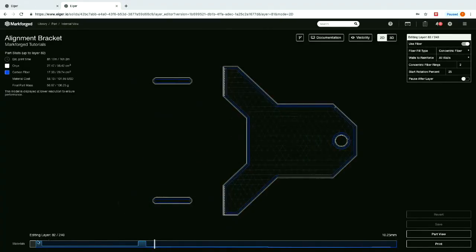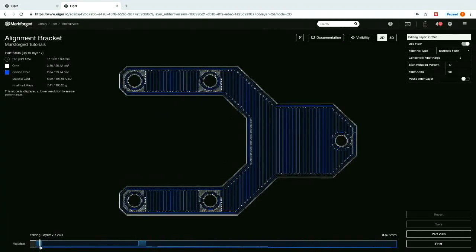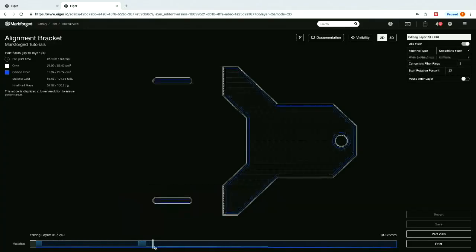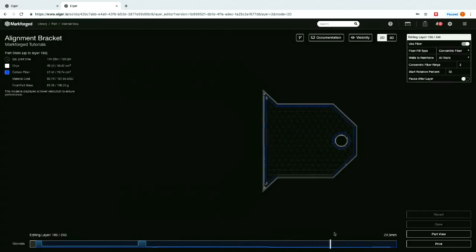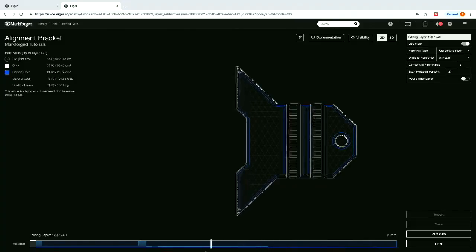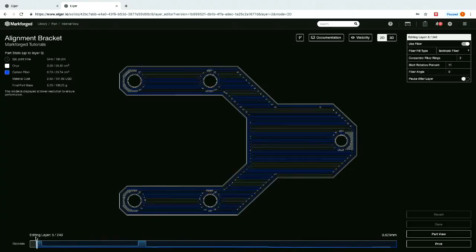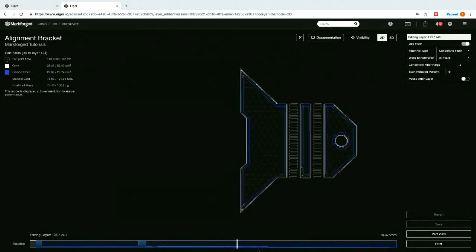What this allows you to do is go on a single layer granularity and go throughout the entire part to see how the part is sliced. Yep. And so 3D shows you the overall view and allows you to create the groupings. The reason we brushed over showing the fiber view in the part view is because it's a really good intro, and it's a base thing. But when we reinforce parts with fiber, we just toggle the fiber on and then slice it and then go into the internal view and change stuff.